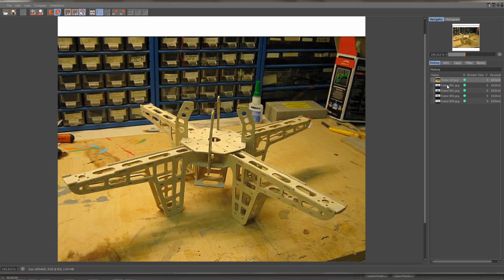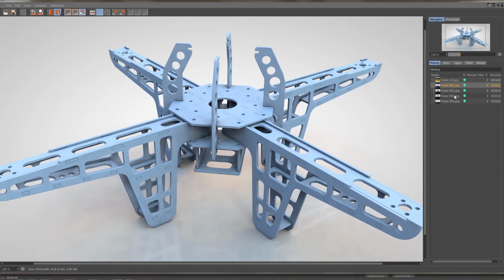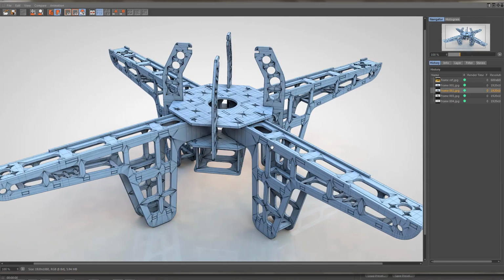And what I did was I created this object here. So this is one of the renders of my final object, and for my version I extruded the splines from the Illustrator file, and then I remodeled everything trying to create proper topology. We're not going to do that in this video because A, it would take too long, and B, the splines actually provide more flexibility. We have a lot of these round areas here, and you can set the splines to be higher resolution or lower resolution depending on what you need. So we're only going to work with the splines. We're not going to create a polygon version of this object like I did here.